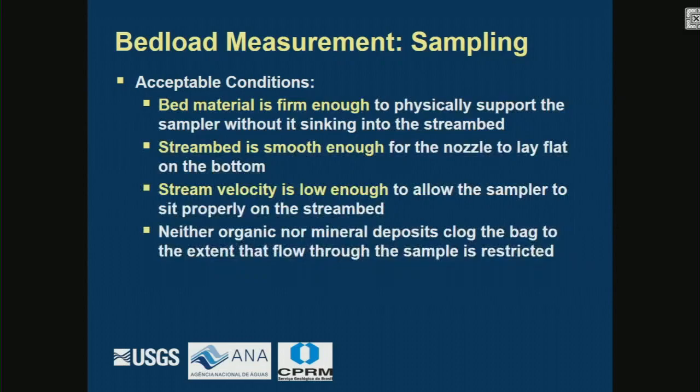If you lower it to the bed and you end up on a rock or something, and you can't get that thing to sit well on the bottom, that could cause a problem. And the stream velocity, you can get by with adding more weight to deal with that. The one thing that you might not get by with is organic material in the stream. If you have leaves or debris coming down, that would clog the bag before you even get to the bottom, which could be a problem.